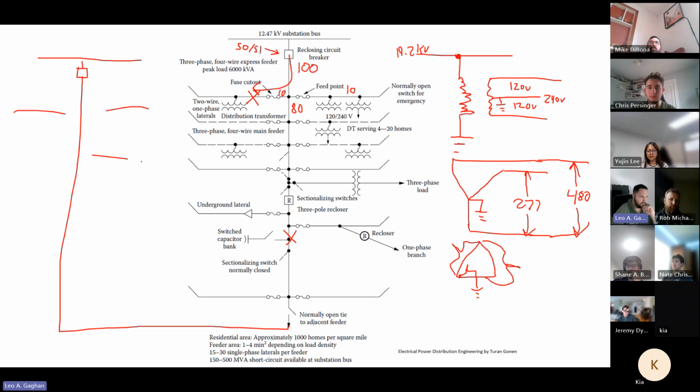They'll have all the radials attached and everything. And what they'll actually do, say, okay, we got to take this breaker out of service. We got to do maintenance. We're going to take it out of service. We're going to close this tie. And then we're going to feed everything from this circuit. And it's really going to see double the load.